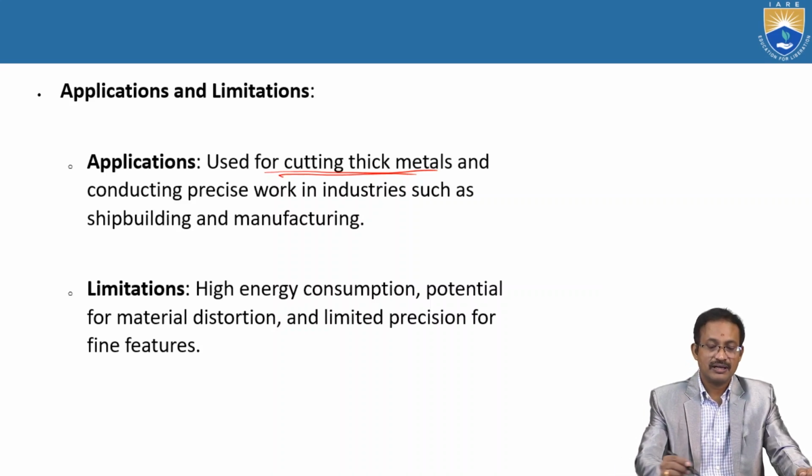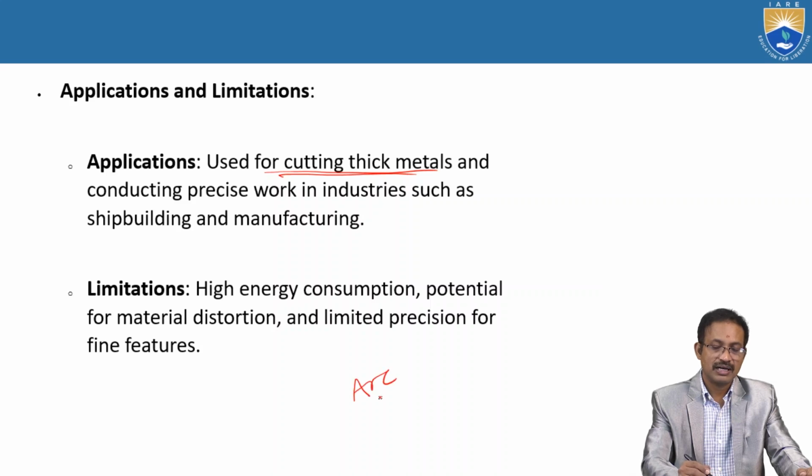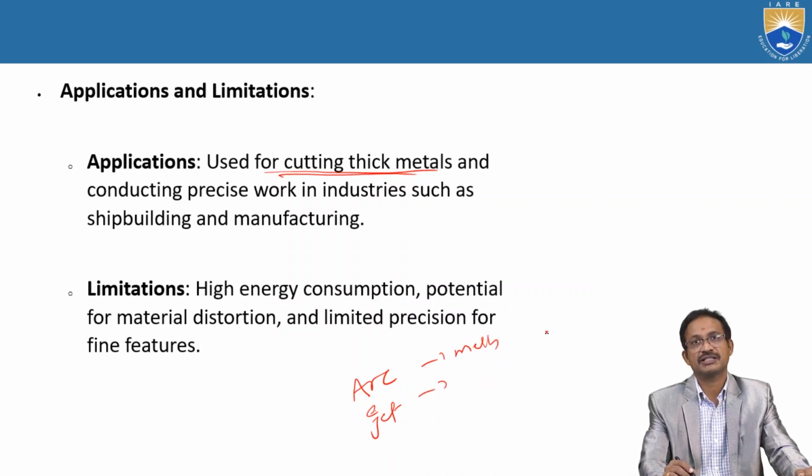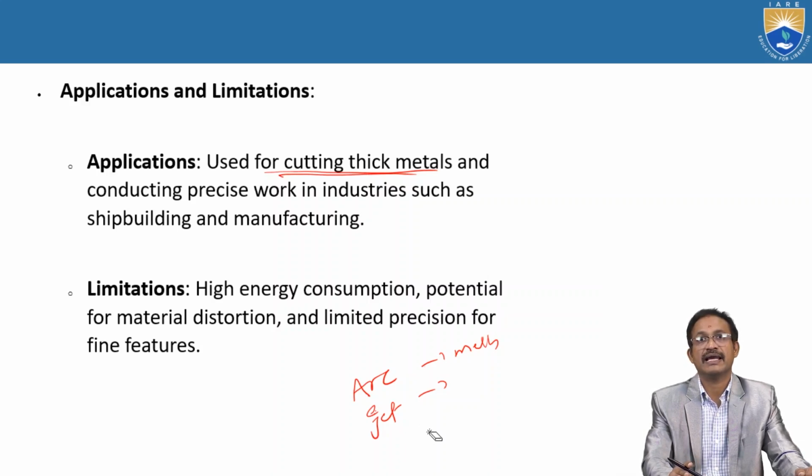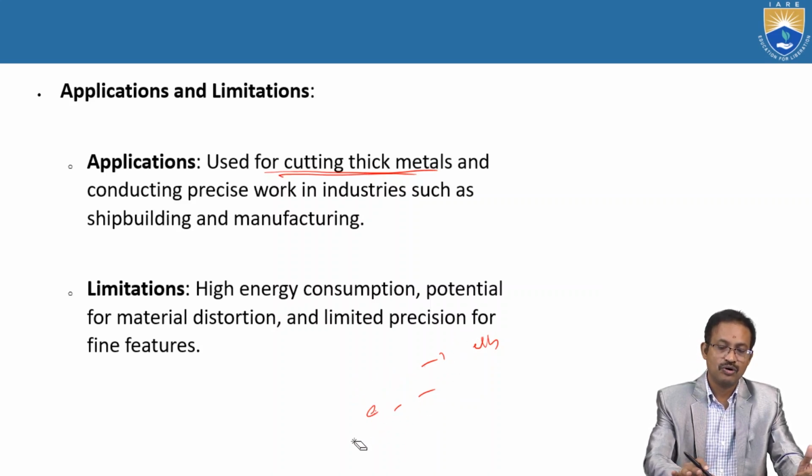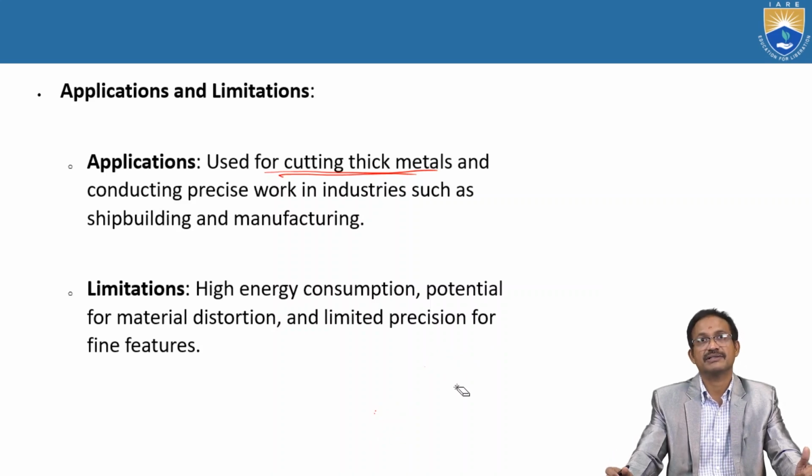Here, plasma arc and plasma jet. The plasma arc melts and the plasma jet flushes away, just like in the previous process, where the dielectric medium played the flushing role. Here, the plasma jet blows out the removed material from the workpiece.